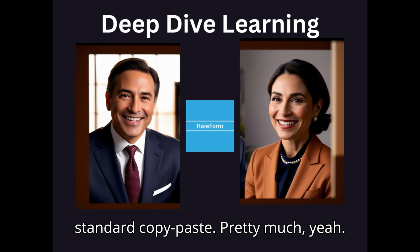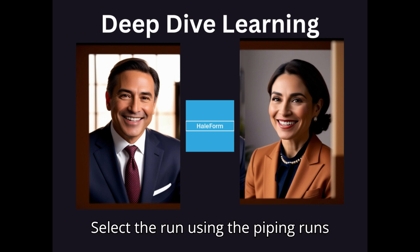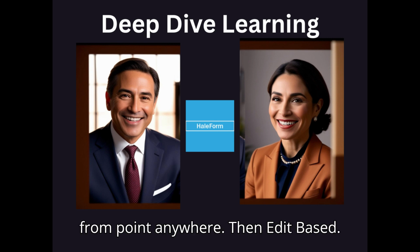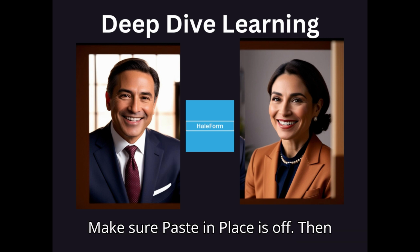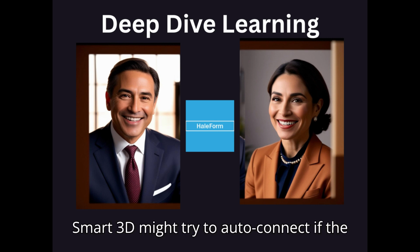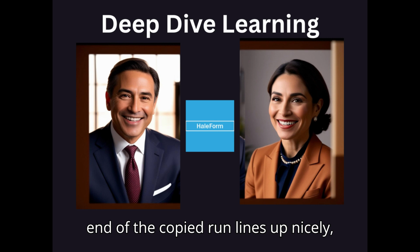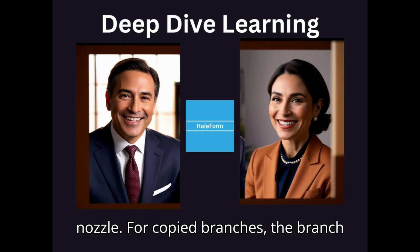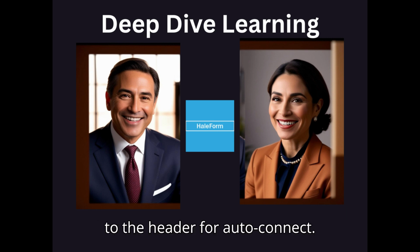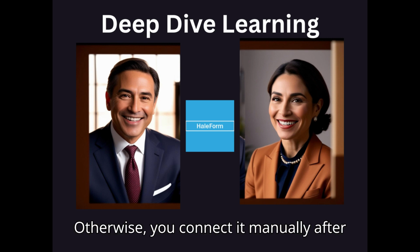Just standard copy-paste. Pretty much, yeah. Select the run using the Piping Runs filter. Use Edit Copy. Pick a from point anywhere. Then Edit Paste. Make sure Paste in Place is off. Then click a to point where you want the copy. Smart 3D might try to auto-connect if the end of the copied run lines up nicely, collinear, with another open end or nozzle. For copied branches, the branch end needs to be orthogonal, 90 degrees, to the header for auto-connect. Otherwise, you connect it manually after pasting.